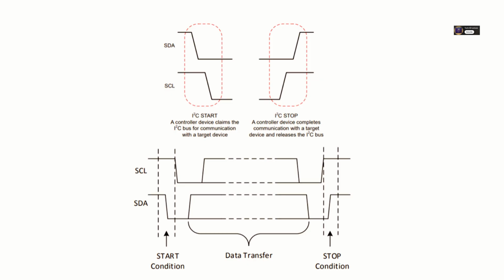So let's walk through the actual conversation, the handshake, step by step. How does it kick off? It all starts with a unique signal, the start condition. This isn't just data changing, it's defined very precisely. The SDA line goes from high to low, while the SCL line is held high. This specific sequence alerts every device on the bus: attention, bus is active, a new transaction is starting.